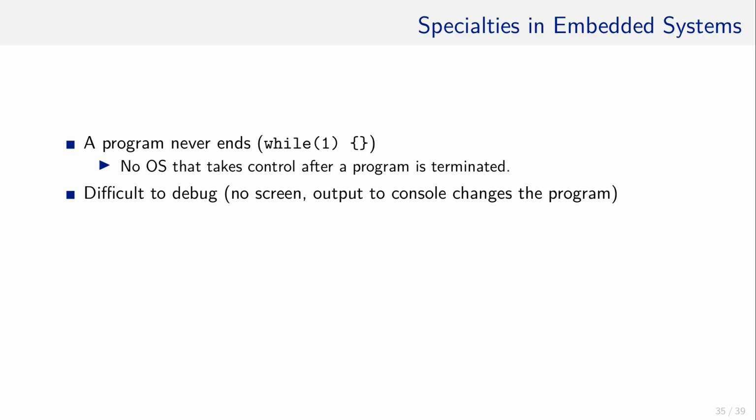A program is also difficult to debug. Many times you do not have a screen and rely on text sent through the debugging serial interface. However, inserting plenty of printfs might alter the timings in your program. It might happen that now protocol timings are violated because the CPU becomes busy printing your debug information.